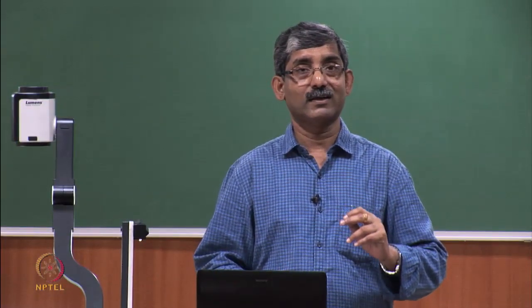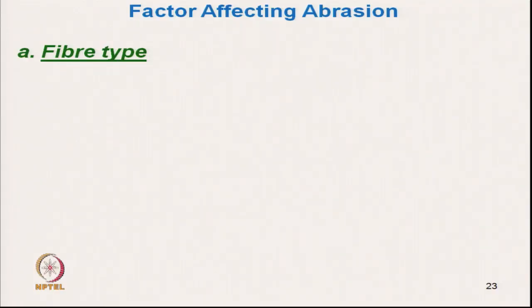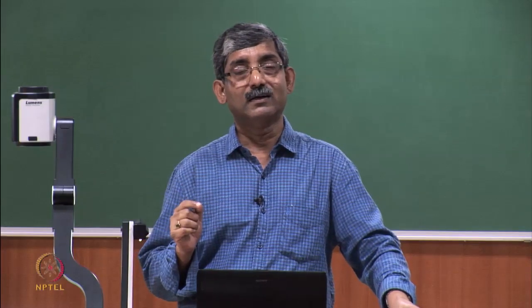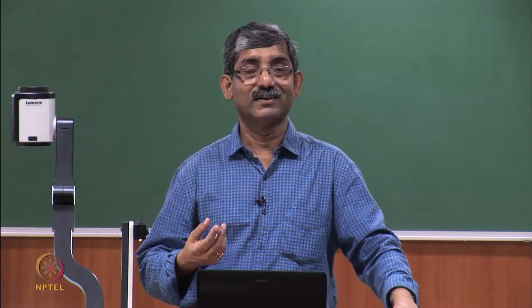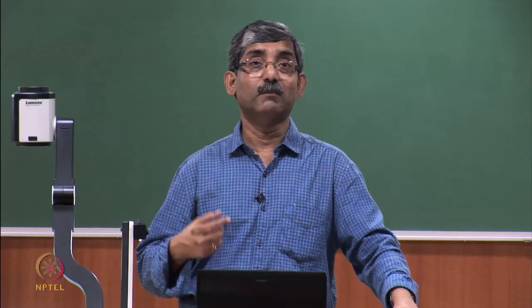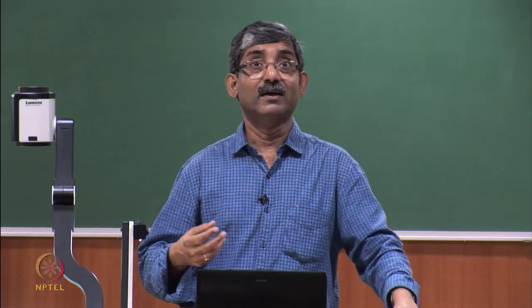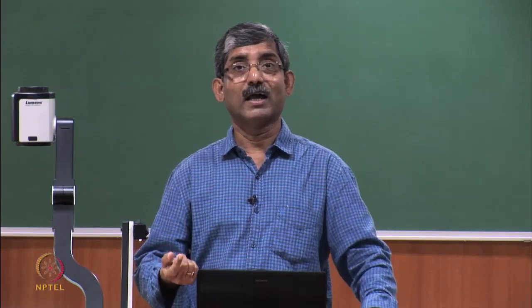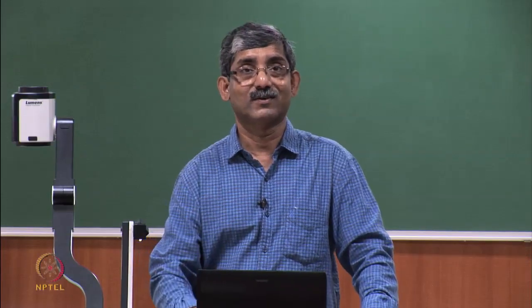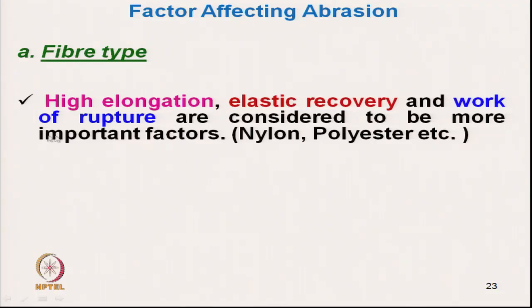Okay. First factor is the fiber type. Now, a strong fiber with higher elasticity will have higher strength, higher breaking energy, higher work of rupture, and will have higher abrasion resistance. Okay. So, high elongation, high elastic recovery, higher work of rupture are considered to be more important factors.